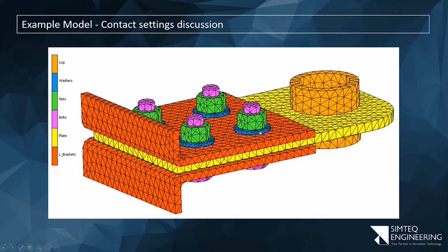Why do I say obviously? It's got the finer mesh. So the finer mesh will always touch the coarser mesh. Now this is actually a bad mesh, to be honest, because for other reasons I may want to make contact from the green to the blue, simply based on I've got a really well-defined outline where the nut touches the washer. But as you can see, the mesh on that is a lot worse than the mesh on the washer. So in this case, if I want to use this mesh as is, I'll be forced to use from the washer to the nut.